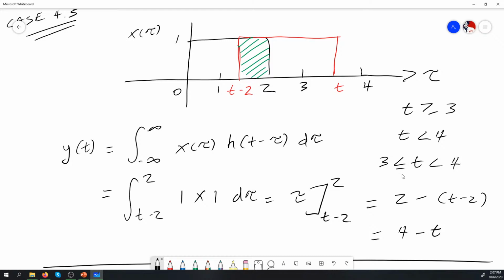So that's why it's very important to always conduct the integral evaluations for each case of the convolution using a time width of 1 unit. So always evaluate your cases with a time width of 1 unit. And make sure that when you're sketching the graphs and evaluating the inequalities, you obtain inequalities representing this time range of 1 unit.